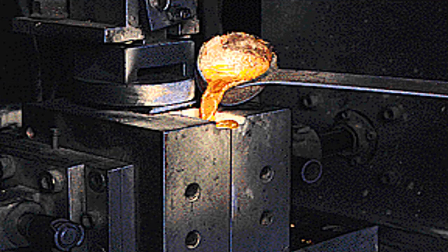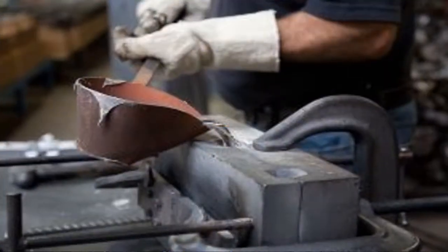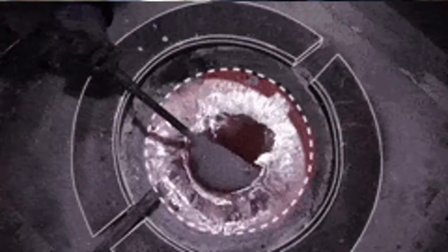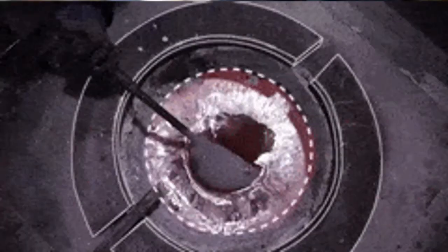Permanent mold casting uses a metal mold constructed of two sections designed for easy, precise opening and closing. The mold used for casting low melting point alloys is commonly made of steel or cast iron, while the mold used for the casting of steel must be made of refractory materials due to the very high pouring temperatures.